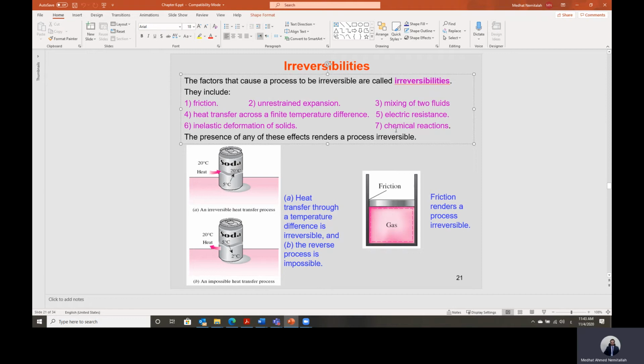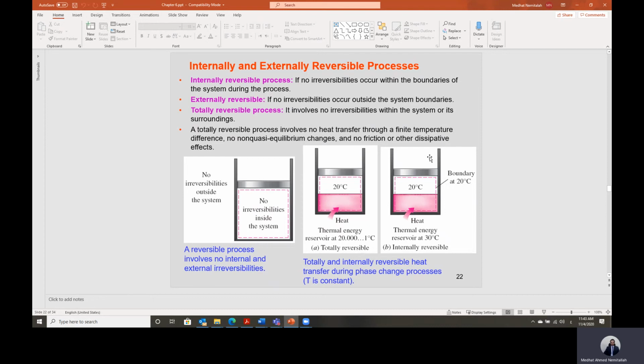So we have converted the fuel into combustion products. But if we add heat to the combustion products, we cannot get back to the fuel again, like the engine of your car. We burn the fuel to get exhaust gases and drive the engine. But if I reverse the process, if we heat up or reject heat from the exhaust gases, we cannot get the fuel back. So in a chemical reaction, some species are totally converted to other species, and this process is also a kind of irreversible process.